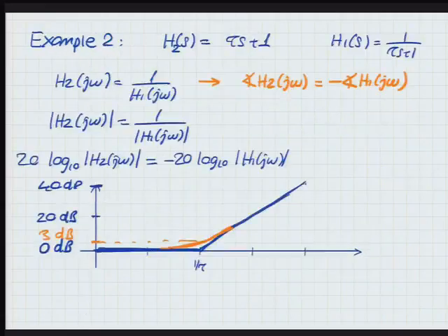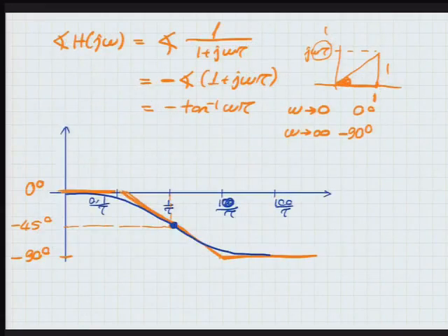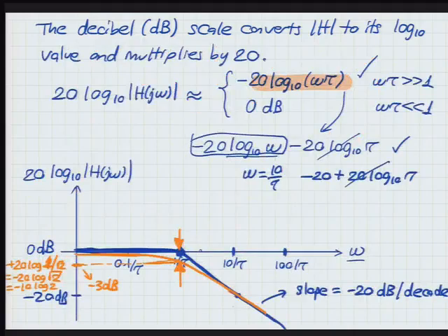I'll be lazy here. Go back to example 1 and tweak that a little bit. So this was the plot for one pole, right? 1 over tau s plus 1. Now I'm looking at 1 over tau s plus 1 squared. So two of those multiplied. Therefore, both the phase and the magnitude need to be doubled, right? So that's why I'm not going to draw this all over again. I have to just change some numbers. And you can help me with that.